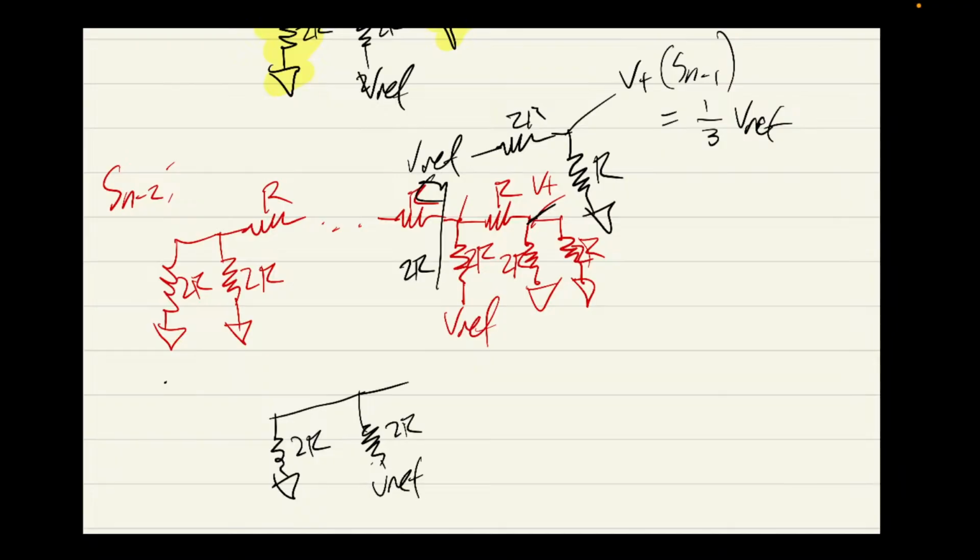And then we have, let's consider the equivalents, R to R. Just before the node, another 2R resistance going to ground. Now we did this exact same problem just previously, and that tells us that this voltage right here is going to be Vref on 3. But that's not the question just yet. That's the voltage right about here at that node.